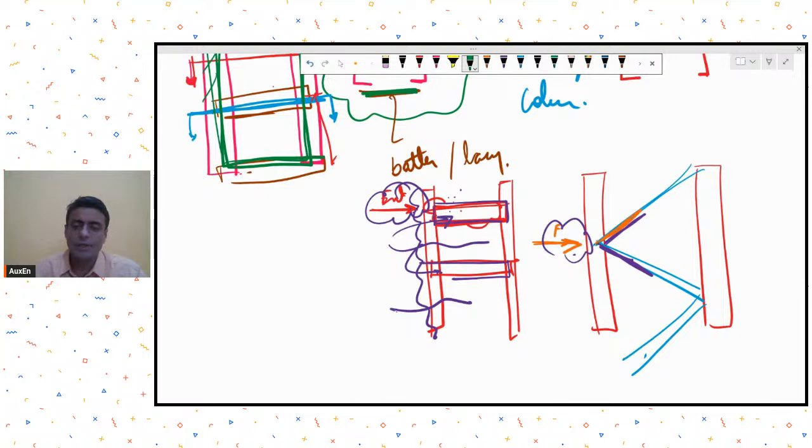So what I will do is I will assume only one lacing is going to take this force. Now that force may be due to point load or due to UDL, whatever. So I'll be doing like this. This is in case there is an actual load acting on the column or on whatever open web system you have created.